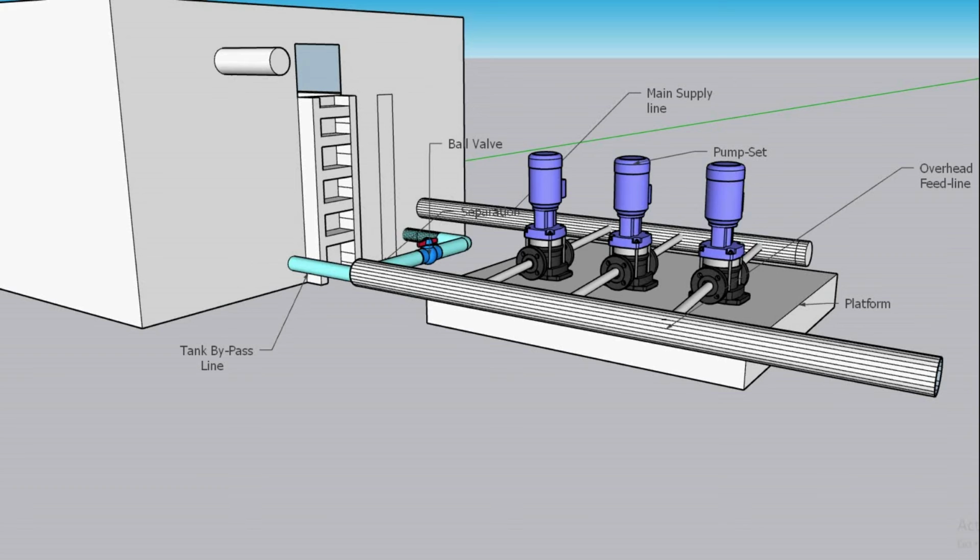So basically, you can work at any working percentage, 0, 1, 2, 3 till 100%. But without a VFD, it's either start or stop. So it saves a lot of money, and it saves a lot of energy wasted on the pump. The lifetime of the pump also increases because of the VFD.